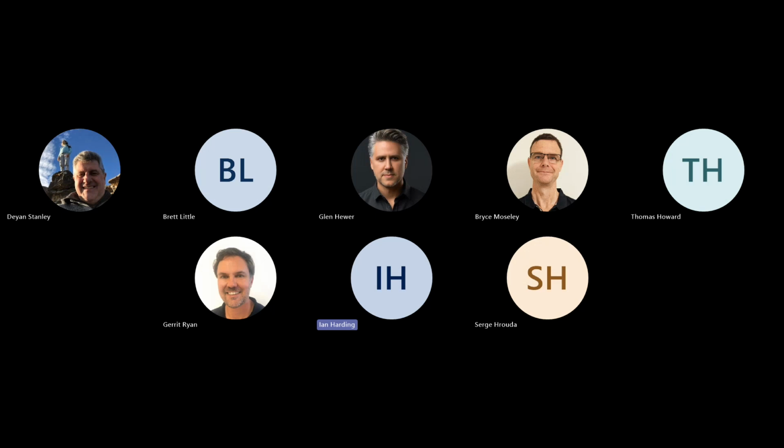The DALI gateway will handle the communication with the emergency ballasts. It will tell them to start the test. And when it gets a report back from the device, it will take the information, send back a DALI telegram, and the software then can database all that. It can give you a start time, a finish time, what test was run, all the sort of information that's necessary to be done. And it can database that and then present a report. It can email reports and do all that sort of stuff as well for you.